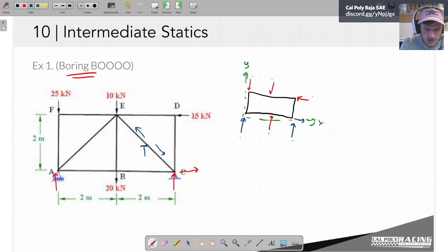It might make sense to start here, because we're given one force and we can pretty quickly see the other force. Well, that one's probably 0 because there's nothing else going on there, because we assume these are 2 force members. Then I might jump down here and say, if I know this one is 0 because it's not taking any load, then this member here has to take all of the X component reaction from this corner. So, 2 steps, not that bad. We got to it from method of joints.